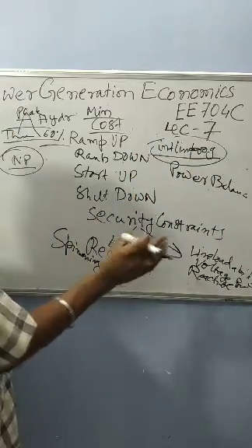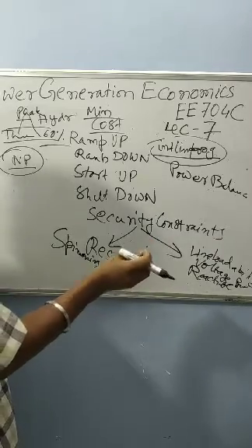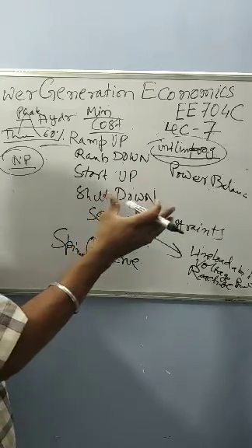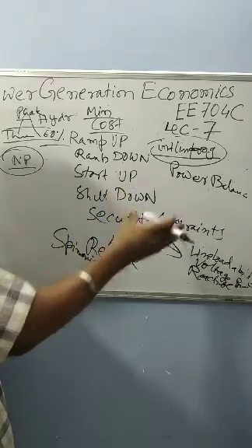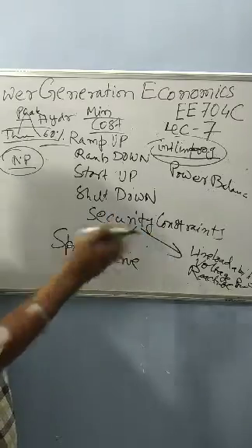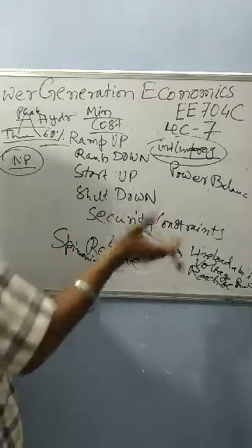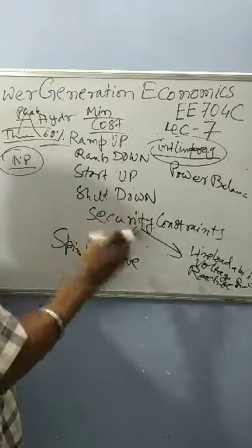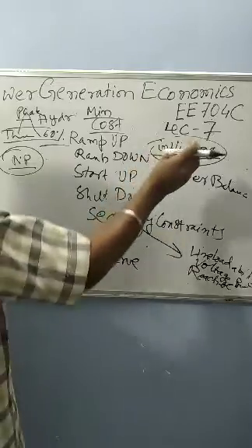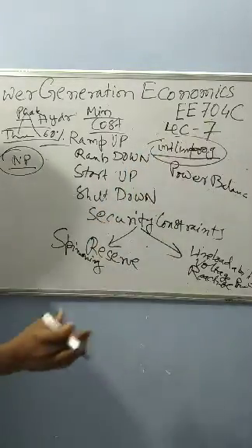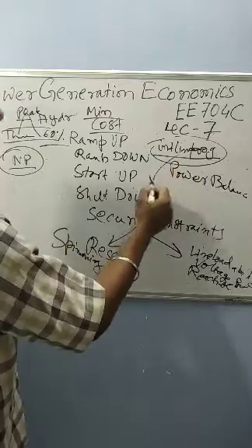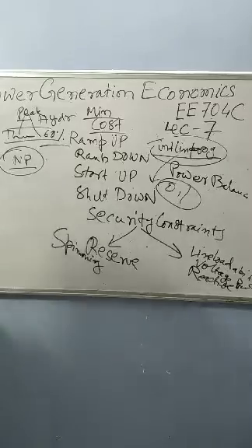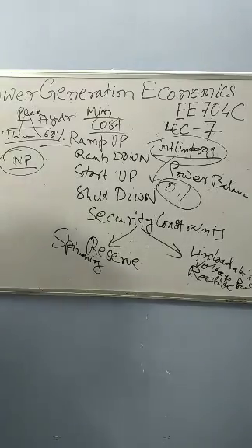we have to make a non-linear function into a linear function, just as Newton-Raphson and Gauss-Seidel are non-linear methods, but DC load flow is a linear one. So we have to change to the DC approximation, and we have to solve by integer linear programming methods, where the values will be either 0 or 1. That is what we discussed in the last class, that it may be a binary programming method.